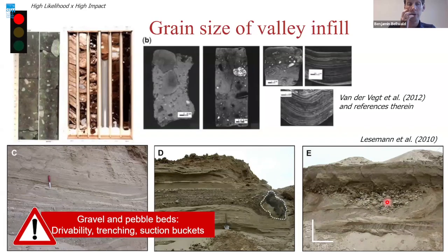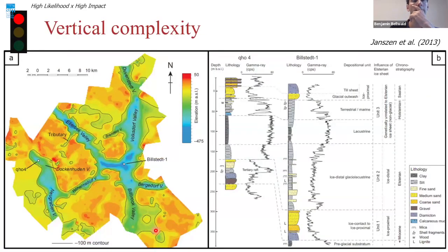And if we hit these layers, obviously gravel and pebble beds have an impact on the drivability, on the trenching, and also on the suction buckets. That's the key aspect that it hits when you're dealing with this, especially with gravel and pebble beds. I'm going to have a slide on boulders later on separately.